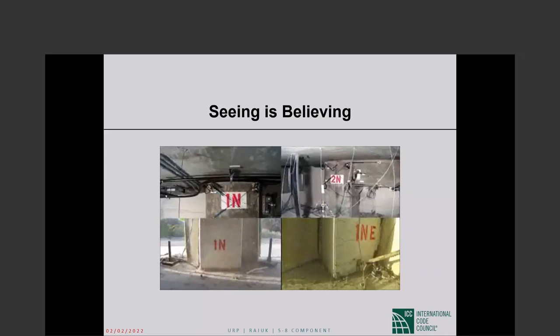Now, when you combine terms, what we will have done is increase the dead load factor from 1.2 to 1.2 plus 0.2 S sub ds. If S sub ds is equal to 1, the dead load factor will now be 1.4 in recognition of vertically downward earthquake ground motion.